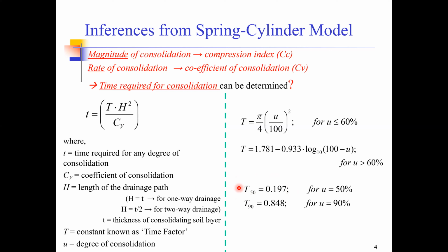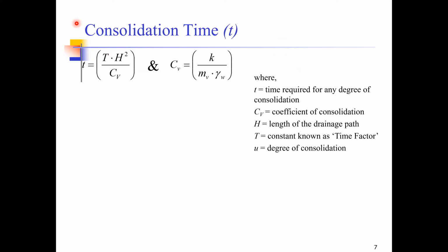So knowing this, we can explore a little bit more about the time required for consolidation, which is also called consolidation time. So this is the expression we have studied on the previous slide, and this CV can also be determined by using this expression.